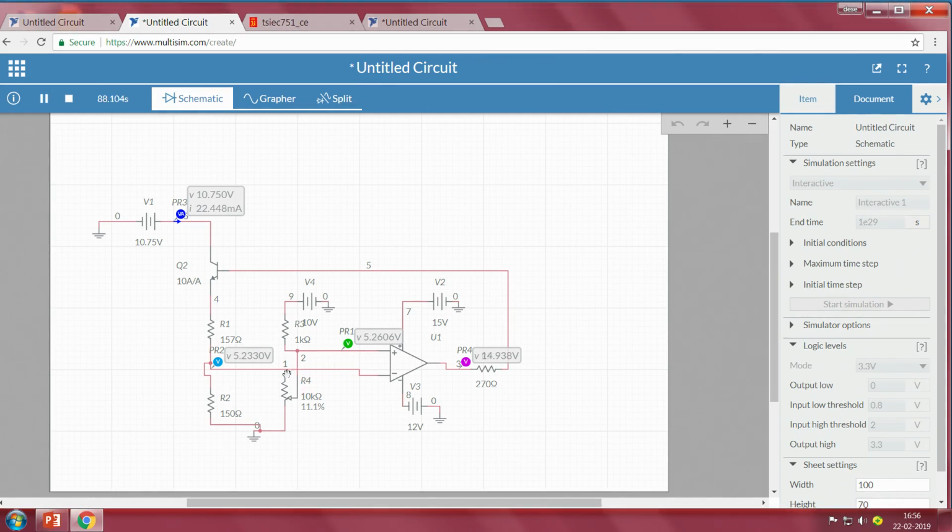Now this is case study 1. I am talking about room temperature 30 degrees Celsius, and I have set the compensatory circuit accordingly. Now what happens? These are a few voltages and currents. You can always monitor at different points of your circuit what voltage and current is being driven throughout your circuit. You can see this is 5 volts. Ideally, if you assume 5.2 and 5.2, the bridge is almost balanced.